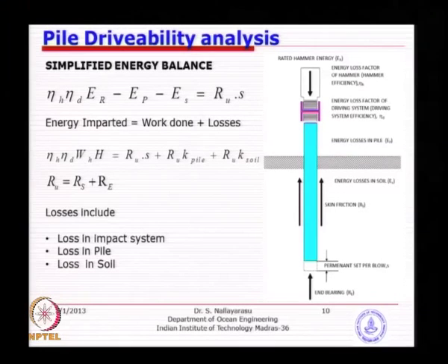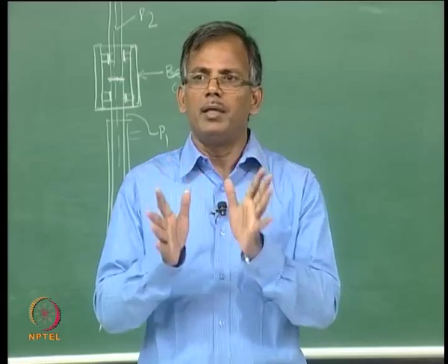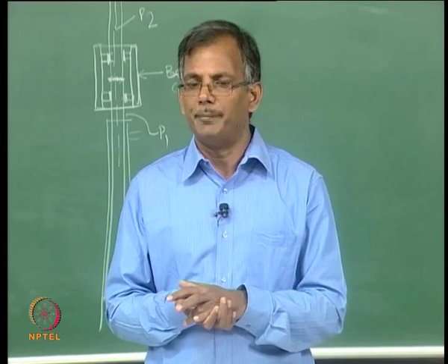Then after that it goes to the soil, and because of the soil failure or displacement, the pile goes down. So that net displacement will be permanent. Basically, it goes down, which means unless you pull the pile out, it is not going to come out. That settlement, sometimes we call it set in earlier terminology, we can call it displacement, which is the permanent deformation of soil that is going to happen.